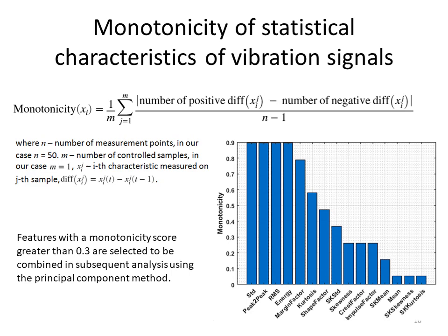The main criterion for selecting the extracted statistical characteristics of vibration signals in the frequency and time domain for further analysis is monotonicity.